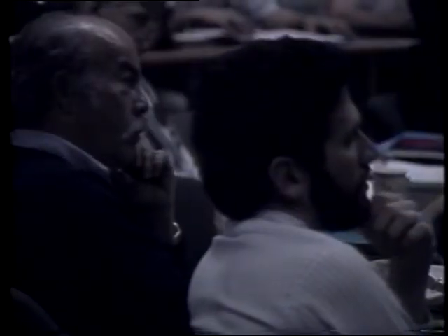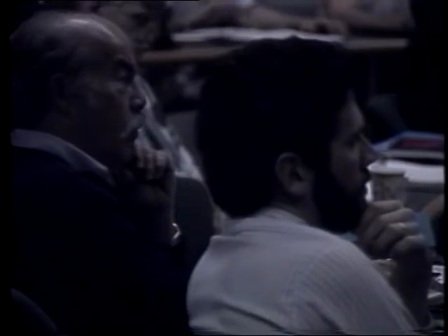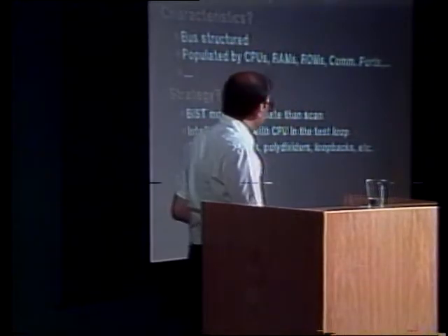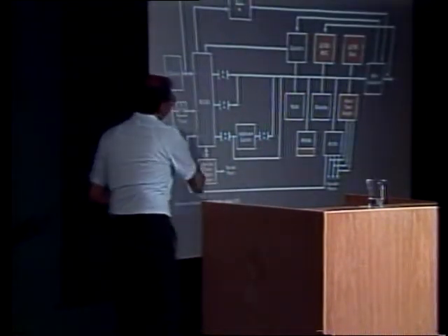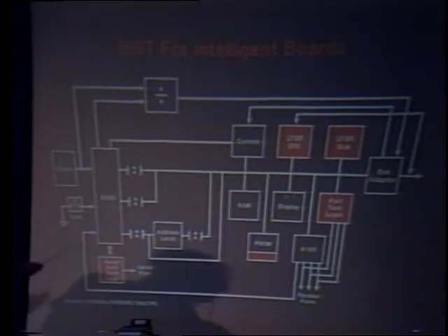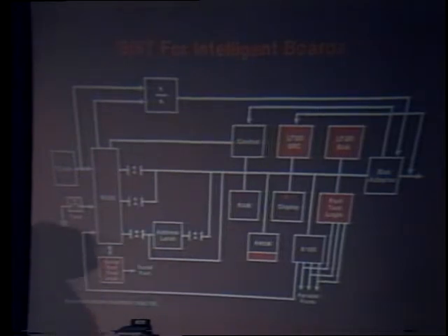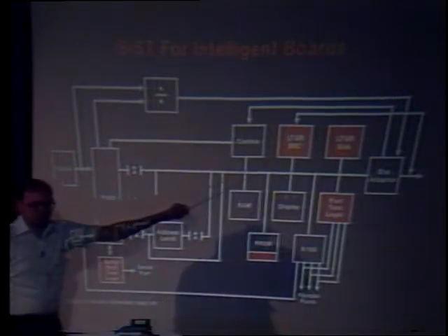However, there is one example from literature called microbit, where they tried to implement linear feedback shift register for the intelligent board. It was an 8085 based system with all those things I mentioned on the board: RAMs, PROMs, displays, some communication ports, etc. In addition, those people, this is, by the way, example from Siemens, they added 2 linear feedback shift registers at the board level.